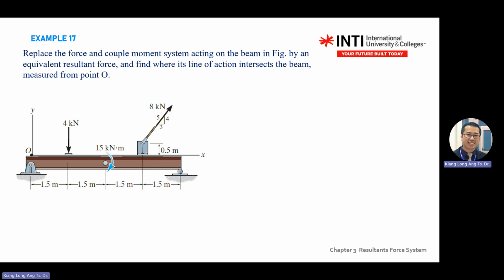All right. So first, you copy the diagram, the shape and the dimensions. This one even gives you the X positive, Y positive direction. Once you copy the diagram, you look at the forces. You split all the forces with angle into XY direction. Once you do, you're done with the diagram with the forces and the moment. You see there's an additional external moment there.